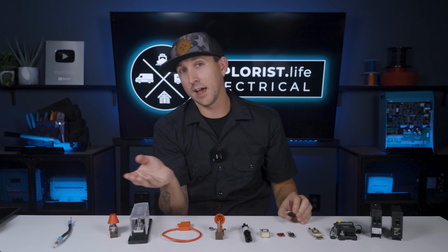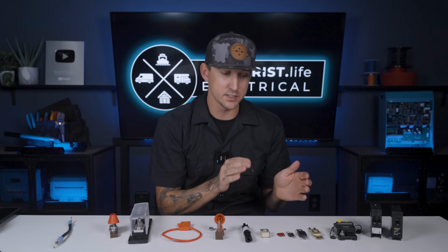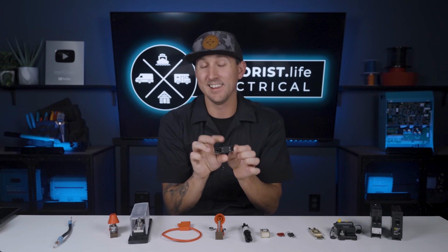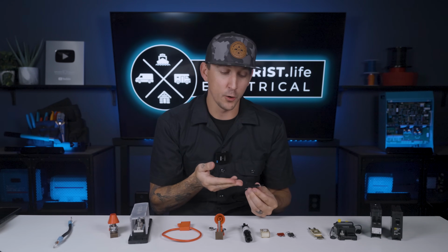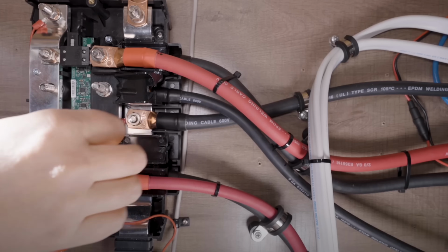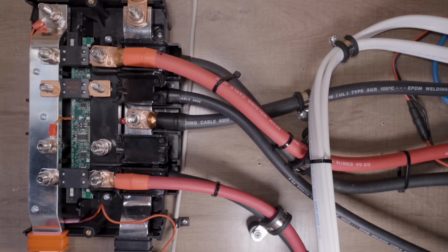Well, because you're not going to have any power coming out the other side, and we can use a multimeter to test if there's voltage on one side and no voltage on the other side. It's pretty easy to narrow it down to that fuse probably being blown. This fuse is used for all of our larger component circuits in all of our systems.